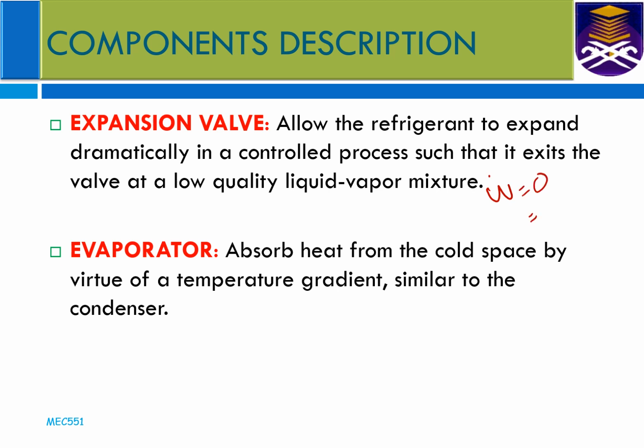Which means that m dot can be maintained, but the enthalpy change will be 0. So the enthalpy H3 will be equal to enthalpy H4, but the entropy will not be similar. S3 is not equal to S4 because the temperature is different.